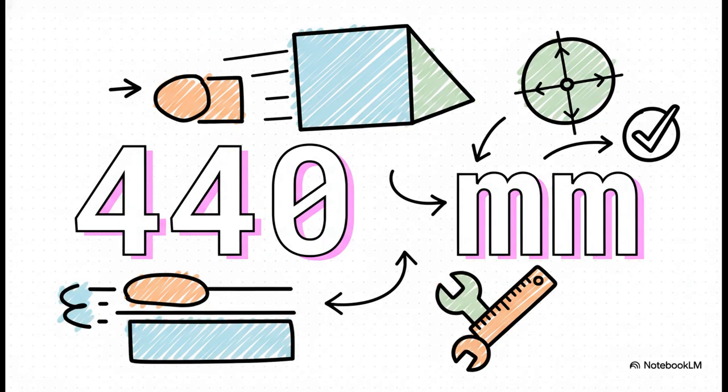Now, we just plug our totals into that simple formula, the sum of the moments, which is 44 million, divided by the total area, 100,000. And what's the result? Exactly 440 millimeters. This is our calculated result, and it brilliantly shows the power of picking the right method. It's not just faster, it also dramatically reduces your chance of making a silly mistake.